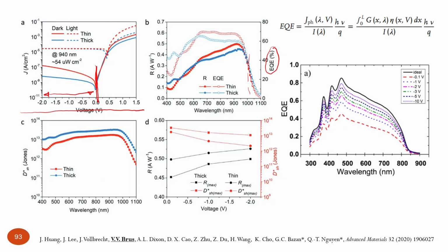So if the band gap is narrow, it actually can create photogenerated charge carriers with longer wavelengths up to this threshold, when photon energy is not larger anymore than the band gap. How do we determine external quantum efficiency? We were talking a little bit about internal quantum efficiency for solar cells, but that's more from a fundamental point of view, because what we can really measure is external quantum efficiency, and we determine it in the same manner for photodiodes and solar cells.